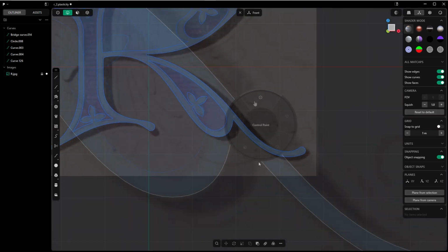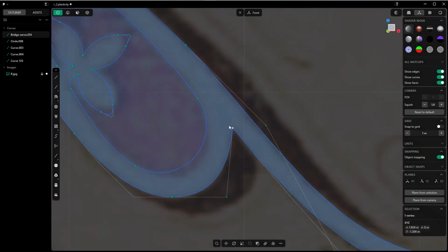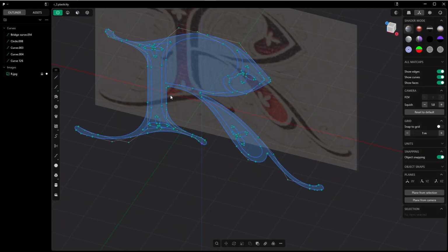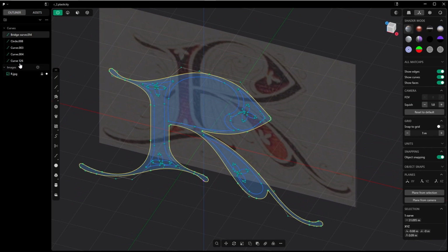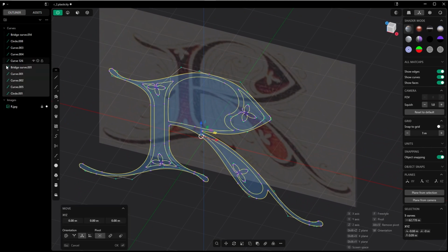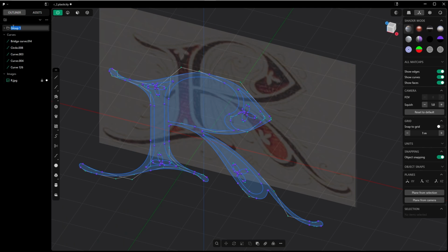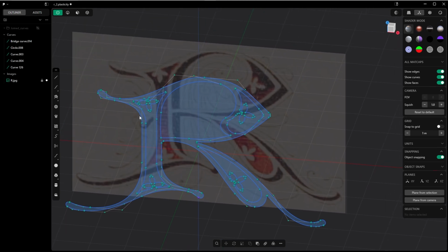So that's okay. Here in control point mode, I forgot to fillet this guy. And before doing any type of rebuilding, I would first like to duplicate these, Shift D, and make a backup, Control G, and I will call this backup folder Joint Curves. And I will deactivate it. And now we are ready to rebuild this.